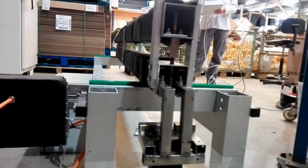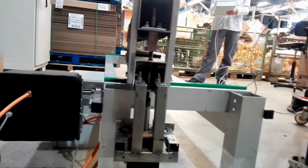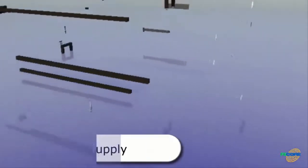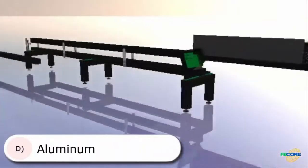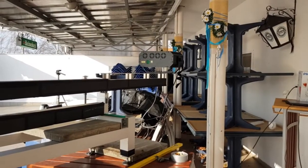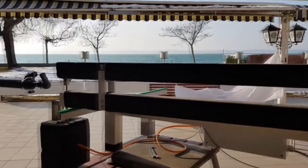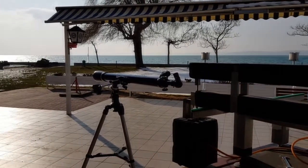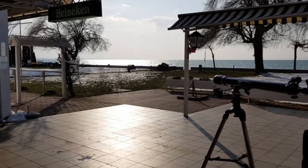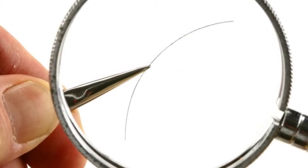The instrument had an accuracy of 54 millionths of a degree in the tilt angle and 34 millionths of a degree in its panning motion. This was accomplished with two high-tech stepper motors capable of making movements as small as 1/10,000th of a rotation. That is equal to 36 thousandths of a degree. This rotation movement was transferred to a bolt with fine threads 1.5 millimeters apart. That meant the rail where the laser was attached could be moved in steps of 0.15 microns. That is less than 1/1000th the thickness of the thinnest human hair.